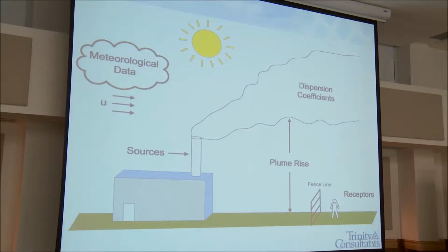With that source data, we can predict the dispersion and distribution of that concentration of odor to areas of concern, which might be a fence line, could be residential areas, it could be condominium top floors. The long and short of it is that a model is always fundamental to the source data. Now, source data is not just involving the stack, it's also meteorological conditions, fundamental. So the first presentation in Australia, they don't have good, accurate, complete met data sets. Therefore, the model might not be appropriate for them. Again, it's a tool, know the limitations.